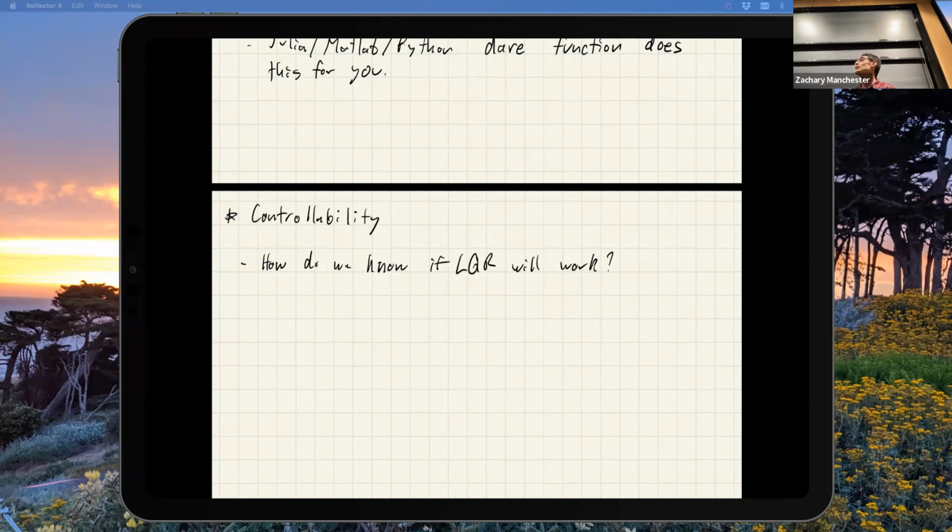Well, no, because there are singular points in the configuration space. So there might be a bunch of these randomly. Don't go there? Well, you often end up in situations where in the normal course of operation, you have to cross through them. There's kind of no way around this. If I need to go from A to B and in between there's a singular configuration, what do I do? I can't get to B without traversing through that, right? So these things can easily become instantaneously uncontrollable. And this is quite common actually.